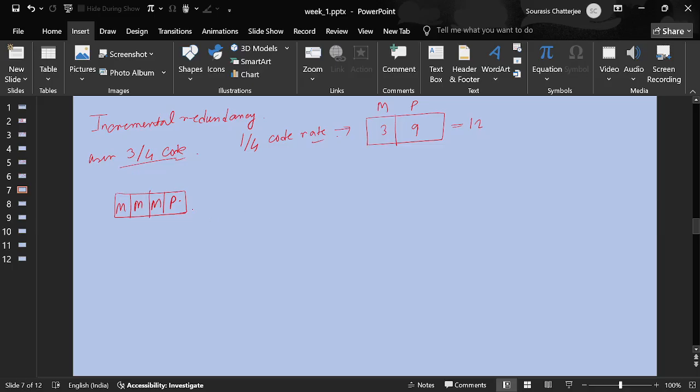So what am I supposed to transmit at the next instant? 4 parity bits. So here the first transmission fails because the SNR is low, so 1 parity bit is not going to be sufficient, so I am supposed to transmit another 4 parity bits, and still 5 parity bits may not be sufficient for proper decoding if the SNR is too low. And what to do in that scenario? Another set of 4 parity bits. We will send another 4.